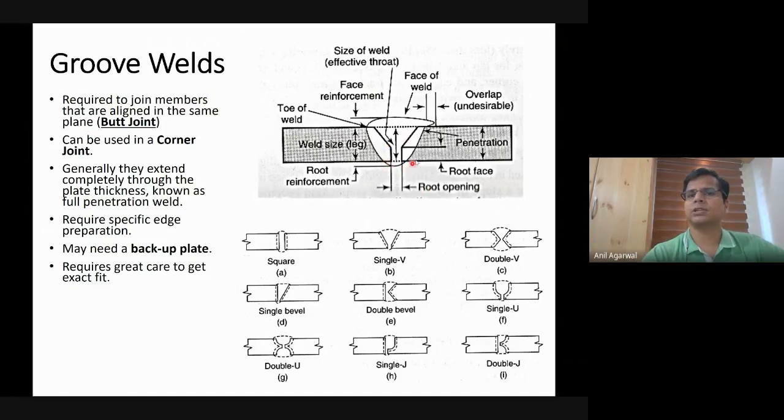Otherwise, let's say your gap is slightly more than what can hold the filler material in place. That may often be the case. So then you may have to put some kind of a backup plate. The backup plate is not welded throughout in the beginning. It is tack welded only at a few locations, maybe 4 locations or 3 locations, so that it is held in place. It is holding the plates in place. And after you are done welding, that backup plate will be at many places fused together with the filler material.